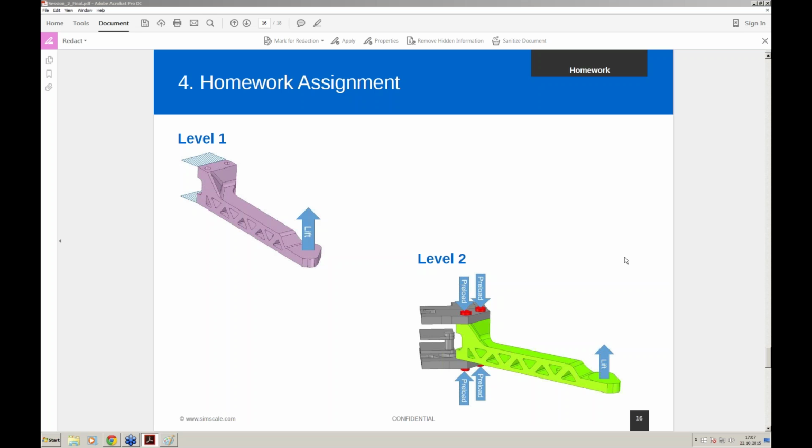So we will have to mesh it once and then create 4 simulations with a given range of lift force, and then you can get an idea how this kind of simulation is, for example, used to optimize a product. Here you're doing 1 meshing job and 4 simulations, and for all 4 simulations you don't have to create them again from scratch. You will just set up 1 simulation, then start it, change the force, and create a new simulation.